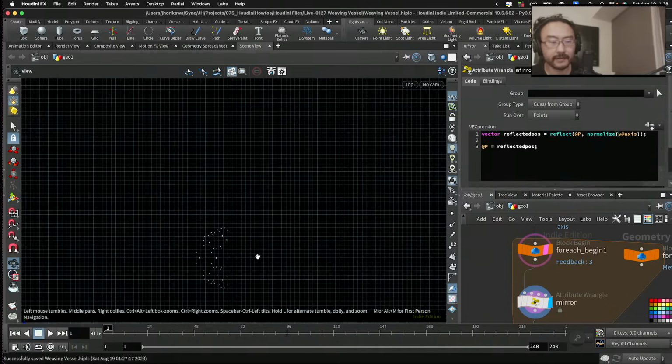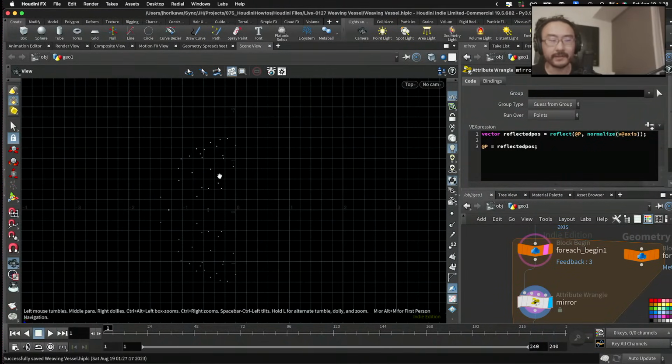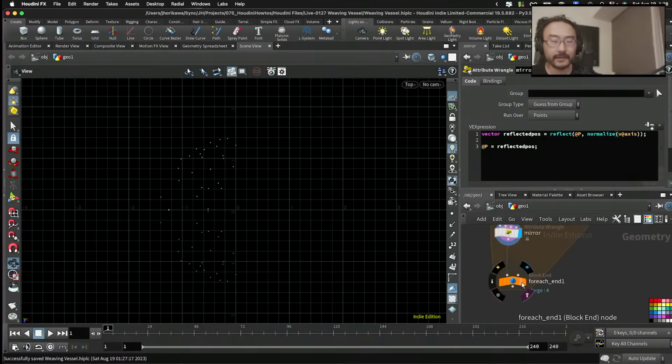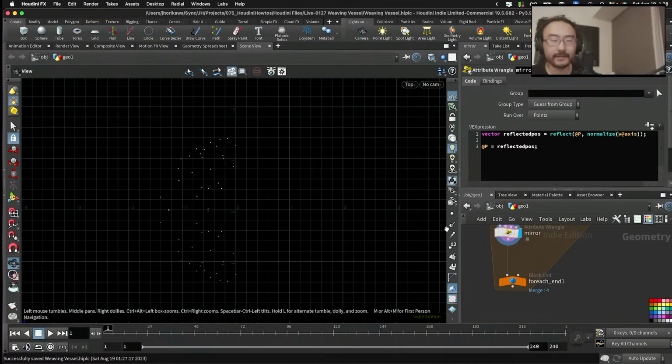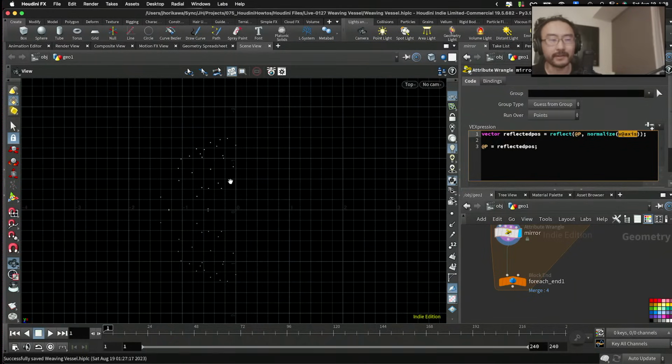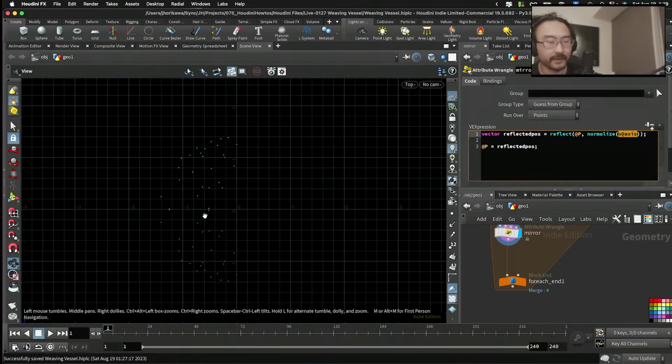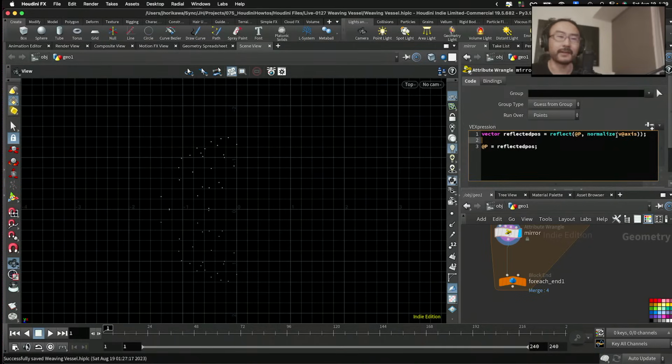Writing like this. Okay. Now this is one loop, but in the next loop I need to change this axis, since in the next loop I want to mirror this shape using this plane here, and this plane's normal direction is in this case the x direction, and you can get that by rotating the z axis, the original axis, by 90 degrees clockwise in this case probably. So you kind of need to update this v axis.